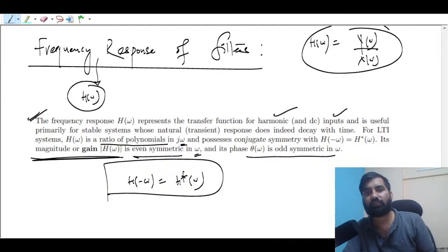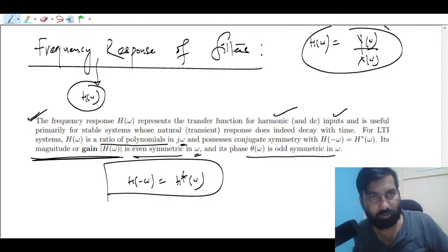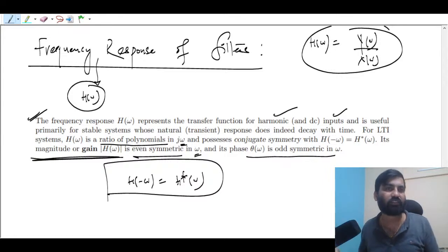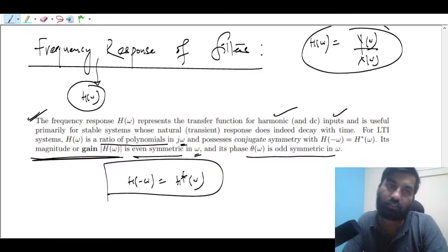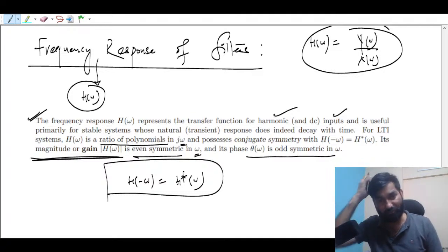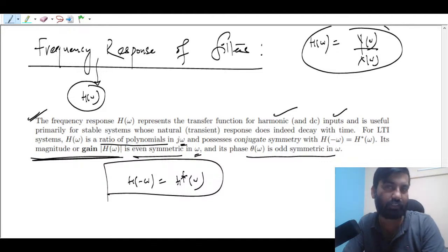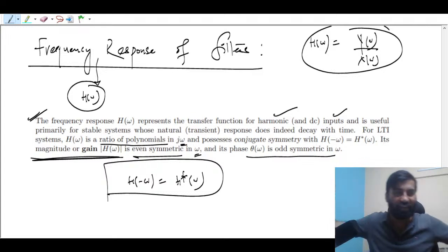The filter is going to be what? It will pass a certain range of the frequency and it is going to block the rest. Okay. So there are different types of filter like low pass filter, right? So it is going to pass the range of low frequency, and it is going to reject all the high frequency guys, right? And if it is a high pass filter, it is going to pass the high frequency and then block the rest. Okay. And if it is a band pass filter, so it is going to pass the band of the frequency and reject the low and the high.